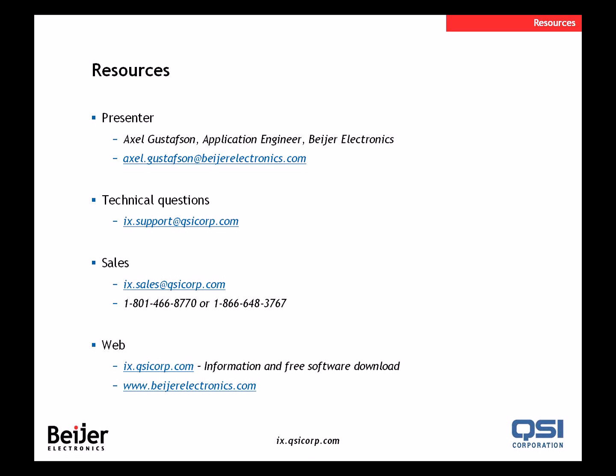Let's see. Jeff asks, what does it do regarding screen resolution on an import? If you have an Information Designer application, what will happen when you import it is that you will create a corresponding application with the same panel. So if you have an Exter T100, you will get an IX panel T100, which has the same resolution.